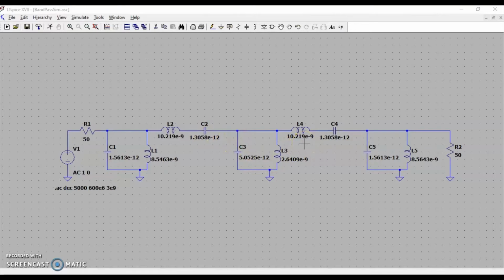And using this method gives us a frequency response that is almost precisely what we want out of our filter. So a couple notes before we get started. We use this setup because the process we use needs a ratio between this resistor here and this resistor, which we call RS for this one and RL for this one, which we'll get into in a moment.